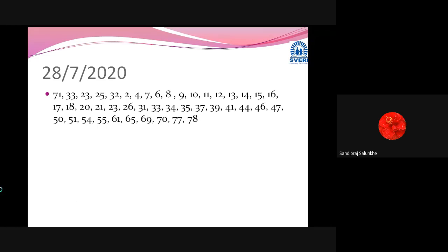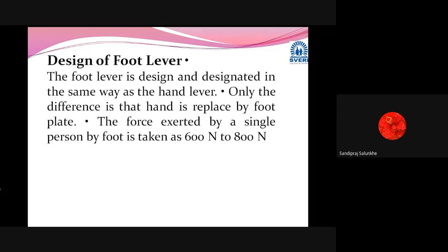Next we are going to see, we have talked about the design of foot levers. Now these foot levers are only differed by considering the force which we can operate or apply on that lever. In case of hand operated levers, this force is limited, okay, up to 300 to 500 Newton. We can apply force with the help of hand on the lever while we are operating that lever.